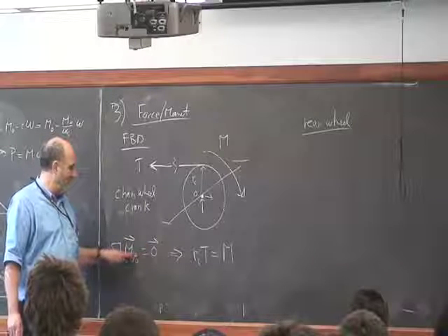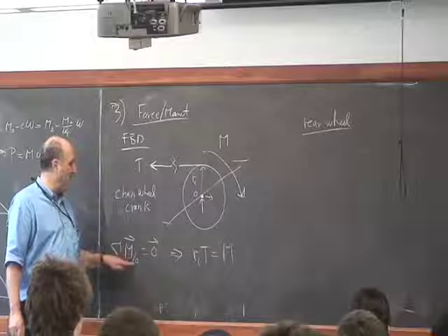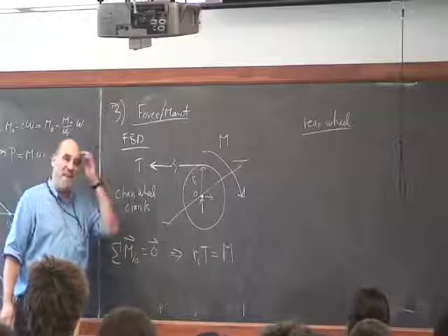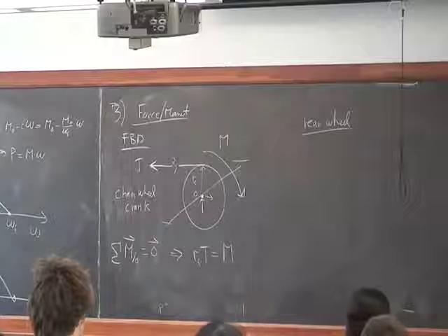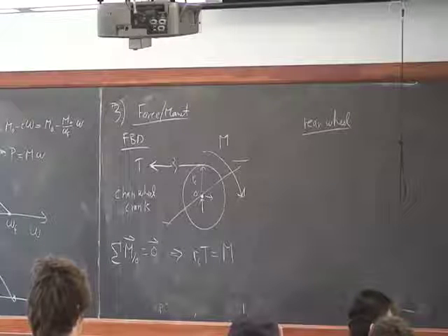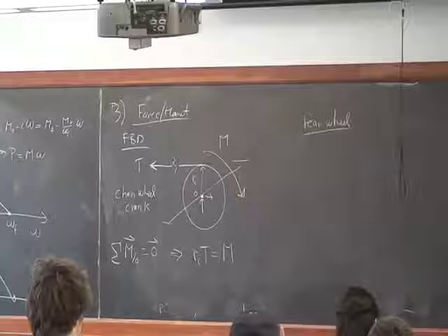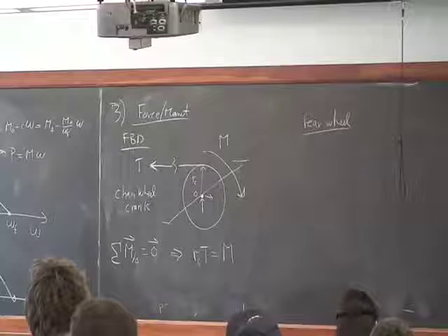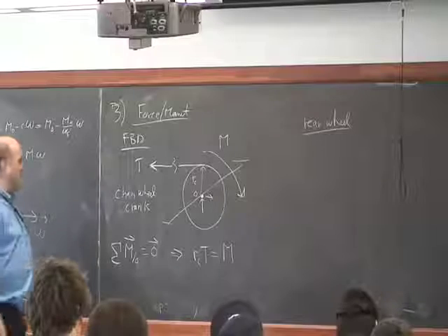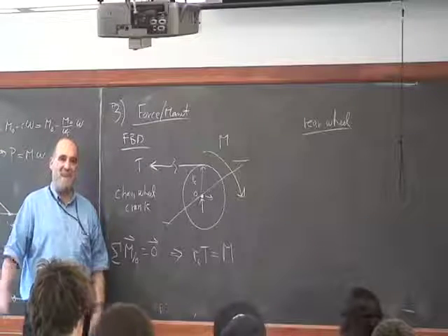Yeah. This means this takes the sum of moments relative to point O. When you have any system, the laws of mechanics apply relative to any reference point, and the sum of moments relative to any reference point equals the rate of change of angular momentum. Basic law of dynamics. The statics approximation is that we can neglect the inertial terms. It says moments have to balance.